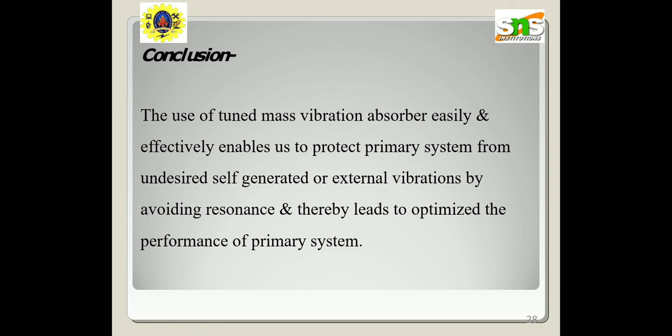And the final one mainly focuses on how vibration is affected by the wind. The force of wind against tall buildings can cause the top to move. These motions can take the form of swaying and twisting, and can cause the upper floors of such buildings to move. Certain angles of wind and aerodynamic properties of a building can accentuate the movement and cause motion sickness in people.